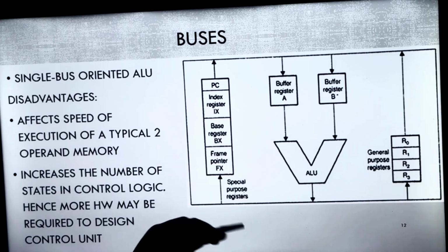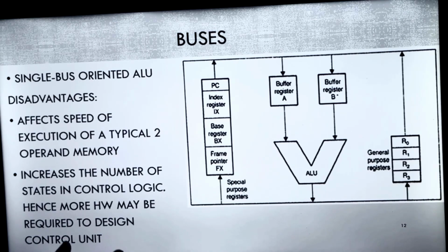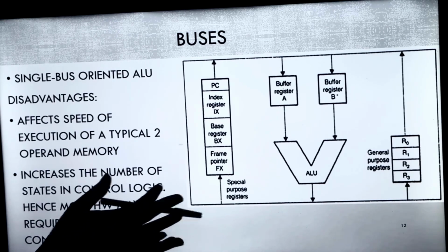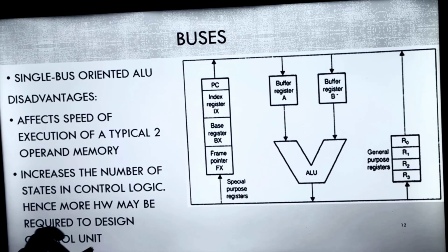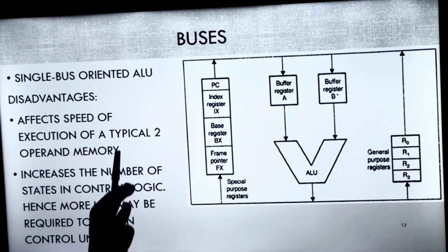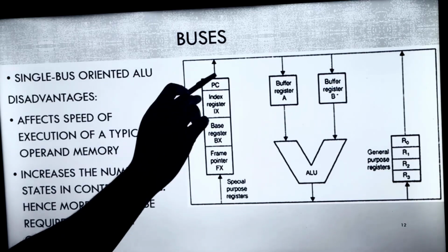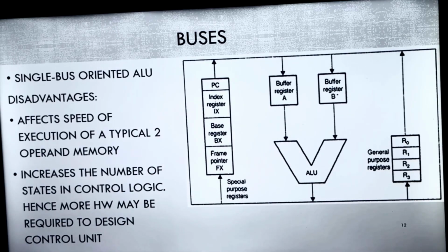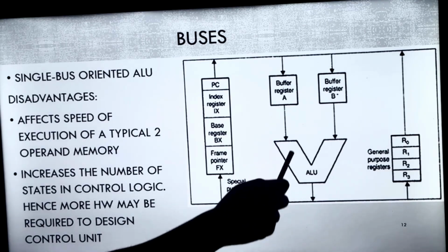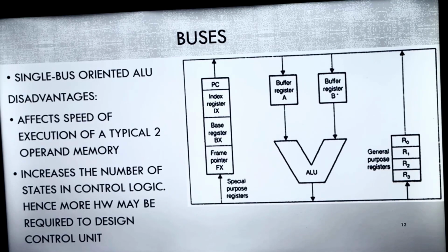So I cannot consider this as a single clock cycle. If you are giving some very complex maths, maybe integration, then so many complex maths, then it may take one clock cycle, but for A plus B, no. So that's why I'm ignoring the time requirement for performing A plus B. So total 3 clock cycles. Fine. One is for A, one is for B, and one is for to get the output. The time requirement in ALU I'm neglecting because this is very simple.